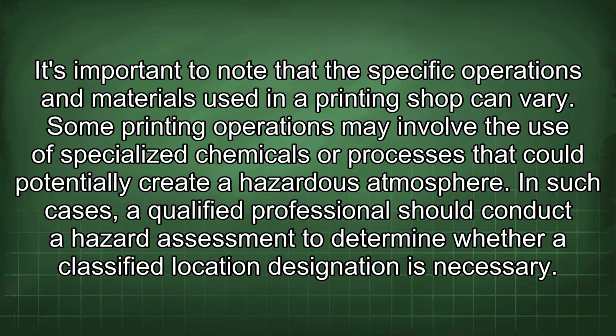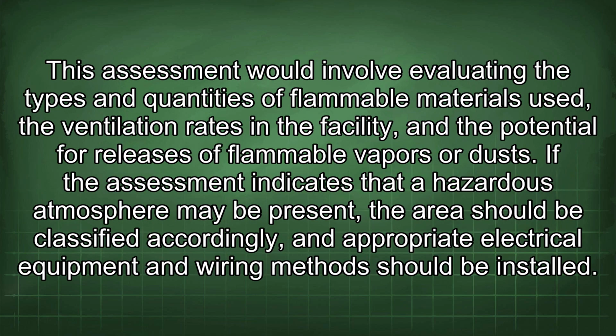It's important to note that the specific operations and materials used in a printing shop can vary. Some printing operations may involve the use of specialized chemicals or processes that could potentially create a hazardous atmosphere. In such cases, a qualified professional should conduct a hazard assessment to determine whether a classified location designation is necessary. This assessment would involve evaluating the types and quantities of flammable materials used, the ventilation rates in the facility, and the potential for releases of flammable vapors or dusts.